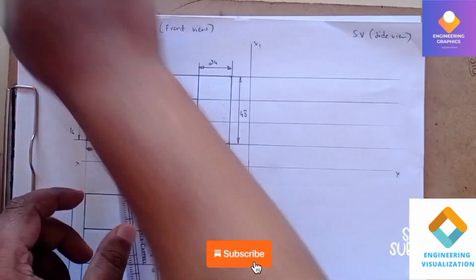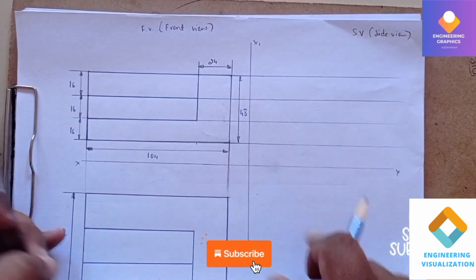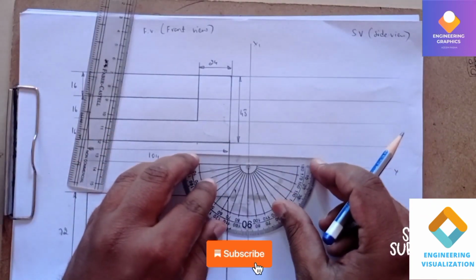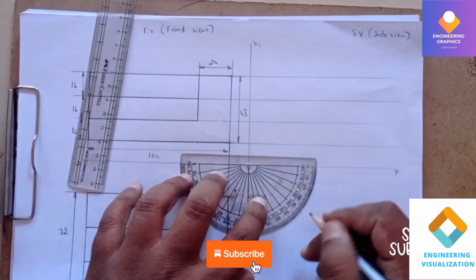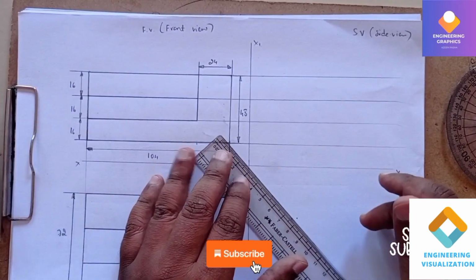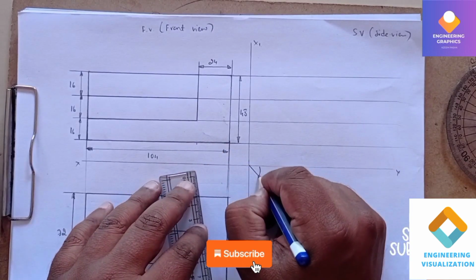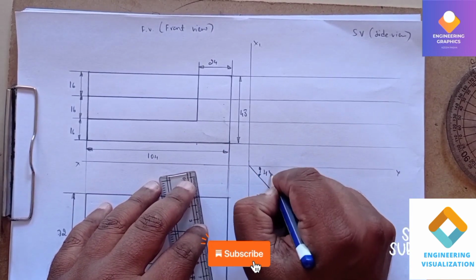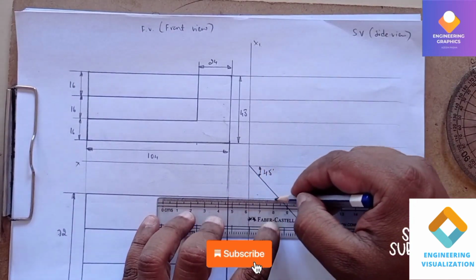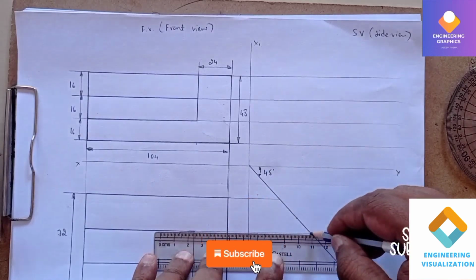In order to connect the side view with the top view, we should construct the 45-degree angle line. So this concept you all know. To connect the top view with respect to the side view, we should construct the 45-degree angle line at the intersection of X5 and X1 Y1. I'll be placing the protractor and marking the angle of 45 degrees. Now draw an angle line passing through this 45 degree mark. Draw a straight line, so this has an angle of 45 degrees. Now project the lines from the top view till they touch the 45-degree angle line.